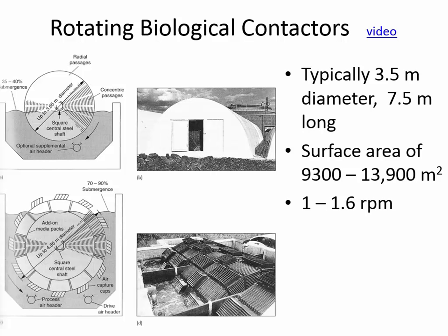In fact, if you aerate the water by doing a couple of diffusers, you could have some vanes, some directional vanes, kind of like a paddle wheel effect, so that the rising air actually causes the RBC to rotate. So that part of the time the RBC is out of the water and part of the time it's submerged.